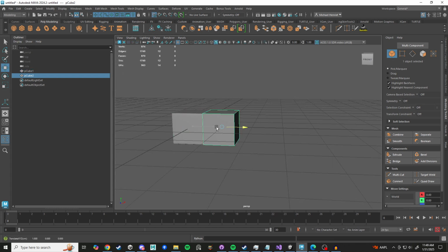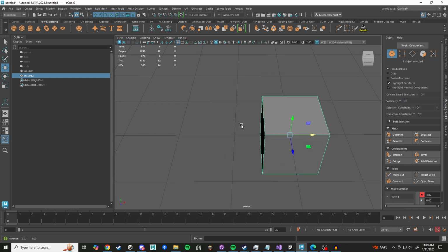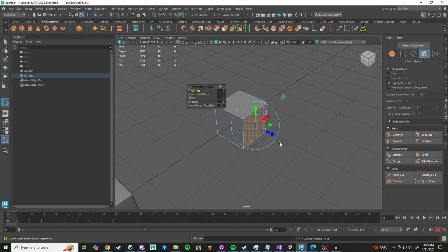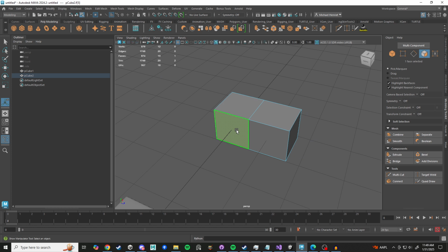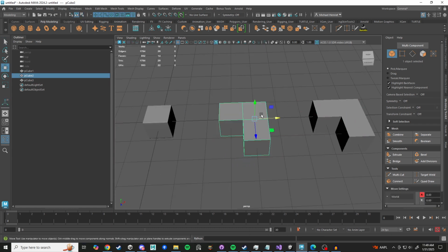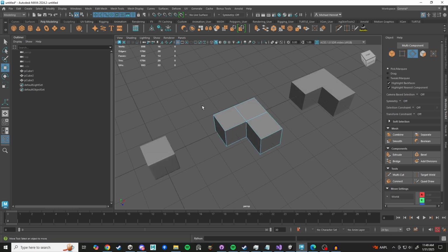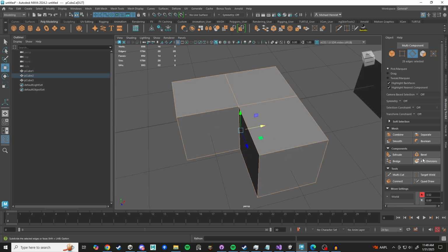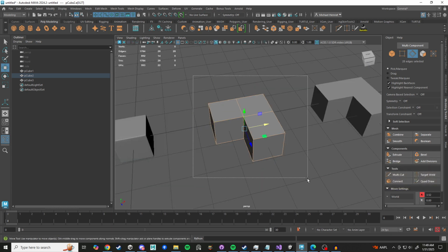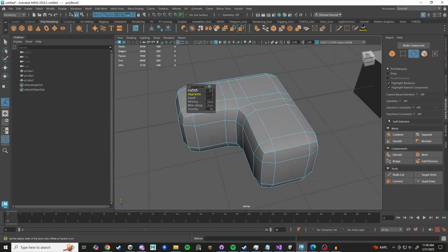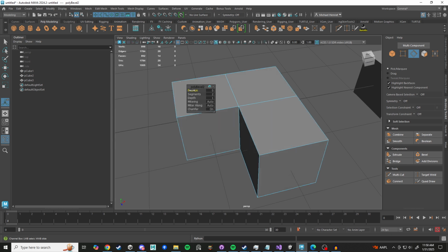Something you have to be careful for is with your bevels. Bevels are not flawless, right? So if I extrude out and extrude out, and let's just duplicate this shape. Let's go into our edges here, and you might be like, all right, I want this shape to hold its bevels real nicely, right? And then you just select your edges, and then you hit bevel, and then let's change the segments to 2, and let's scale down the fraction.